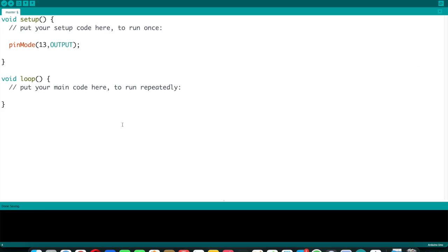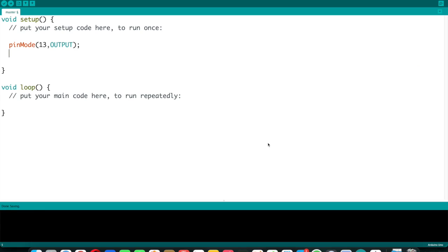So going back, I could find out from the Arduino documentation that physical pin 13 is port B pin number 5. So port B pin number 5 is digital pin 13 on the Arduino Uno board. So instead of writing pinMode 13 comma OUTPUT, which is Arduino C, if I want to do it in embedded C, I would write DDRB equal to DDRB ORed with 0, 0, 1, 0, then 0, 0, 0, 0. Because this is bit number 5.